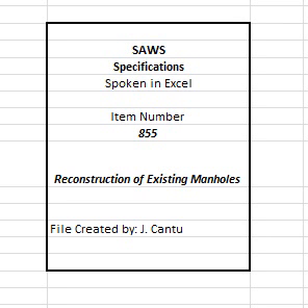2. Holiday testing. Inspect each sanitary sewer manhole using high-voltage holiday detection equipment. A. All detected holidays shall be marked and repaired by abrading the coating surface with grit disc paper, or other hand tooling method. B. After abrading and cleaning, additional protective coating material shall be applied to the repair area. C. All touch-up repair procedures shall follow the protective coating manufacturer's recommendations.